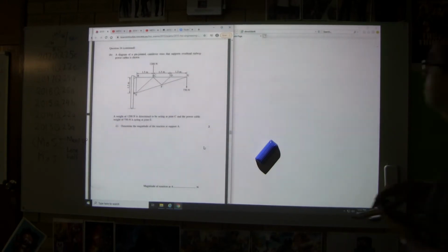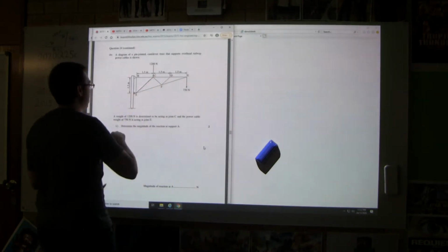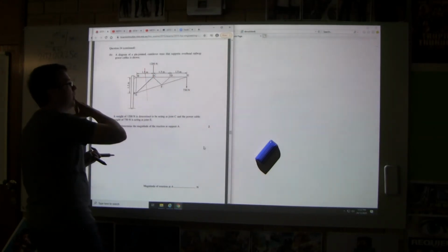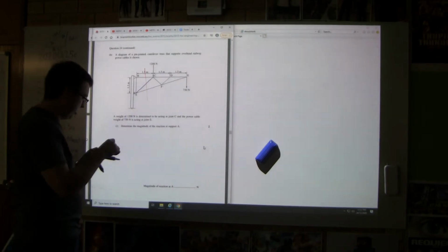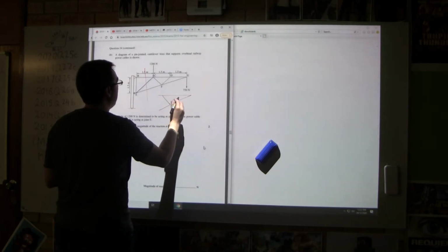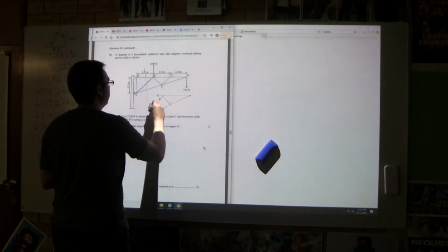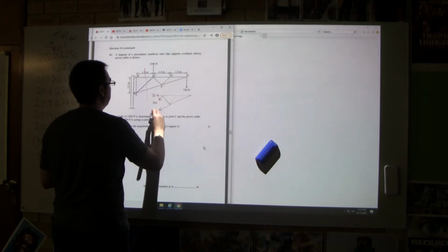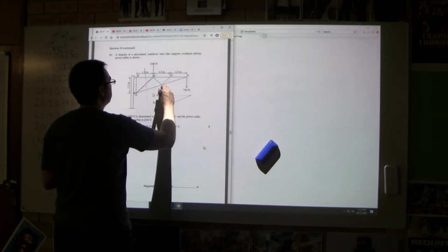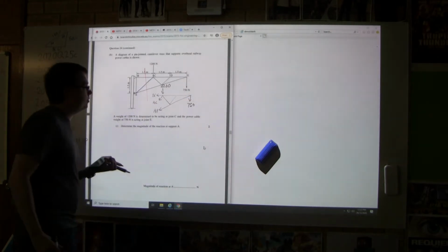Okay. So first of all, this is the member in question. And if I just draw a vertical line, I can see that I get 3 unknowns. Now I could take the left-hand side, but I don't know the left-hand side, so I'm going to ignore that side. I'm going to instead redraw my diagram. And I'm going to draw the forces all pulling out from the node. I've got, let's say, AC, BC, and AF. And I also have a force of 1200 and a force of 750. Okay, so that's my starting point.